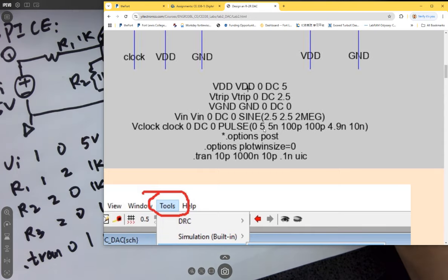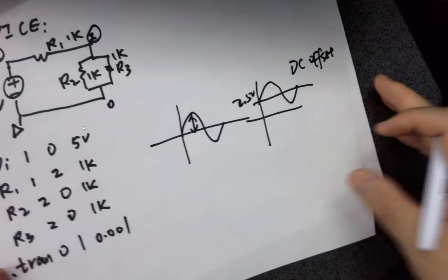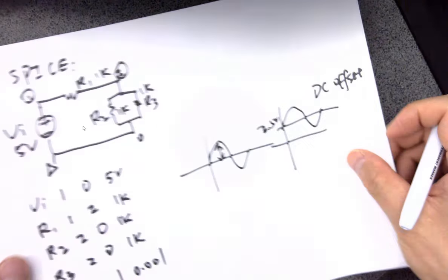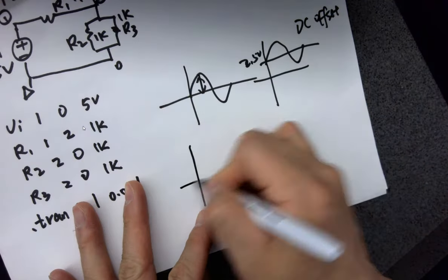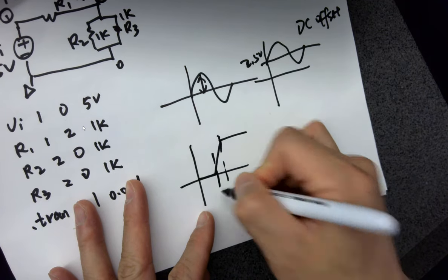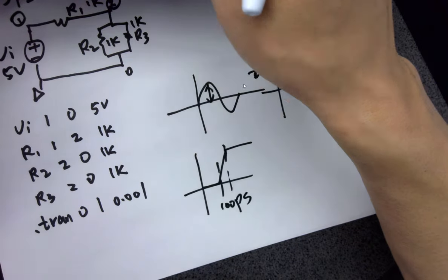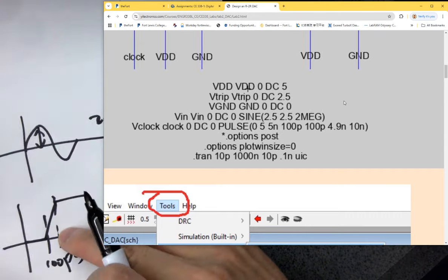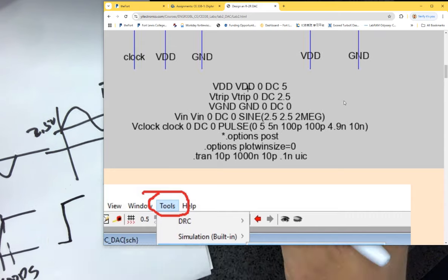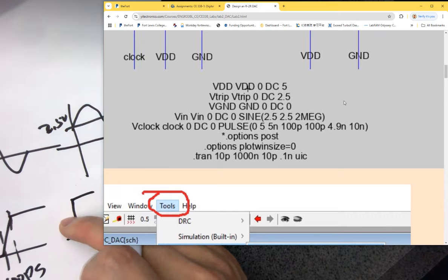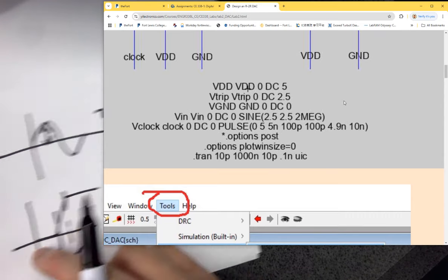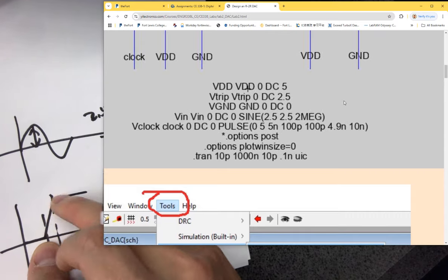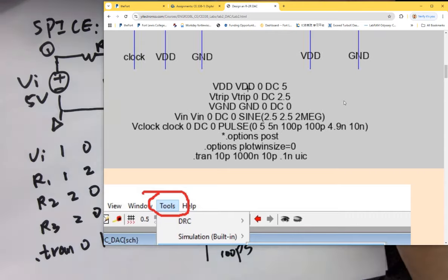And 100 picoseconds for the rising edge. Don't worry about this. This is recorded. Okay? I know I'm going a little bit faster, but no worries. It's going to record it. What's the rising edge? This. 100 picoseconds. Should I make it very long or short? For digital signals, you don't want to make a very significant ramp here, right? Ideally it should be infinitely fast. However, in real life, it won't happen. It does need a time delay, okay? It's a ramp. It takes time from 0 to 5. No matter how short that is, it takes time. So the time we define over here is 100 picoseconds. Rising time and falling time. Okay, 100 picoseconds for each.